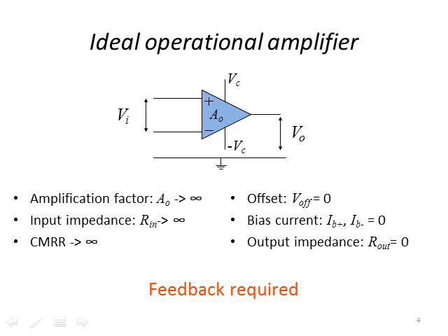the inputs on terminal plus and terminal minus are rejected on the output. The common signals that we see on those are going to be rejected in the output because it's a differential input. The offset voltage, V out, when both of the terminals are set to 0, we assume that the output voltage is 0, and that's not always the case.